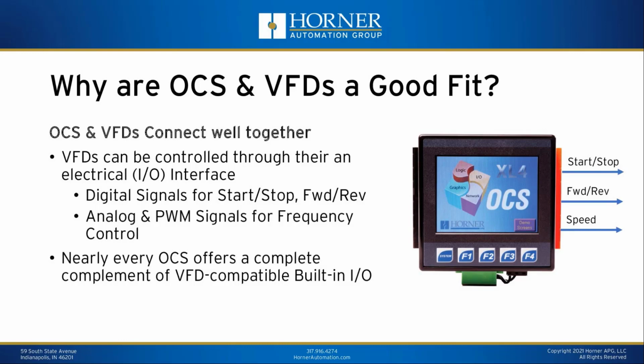Now let's start talking about connectivity between the OCS and variable frequency drives. There are a variety of ways that you can control a VFD. The most common, beyond just turning a pot or entering a number on the keypad, which is pretty much a manual process, and more automatable, if you will, is using I/O signals connected to the terminal block of the drive to start and stop, change direction, adjust the speed, those sorts of things.